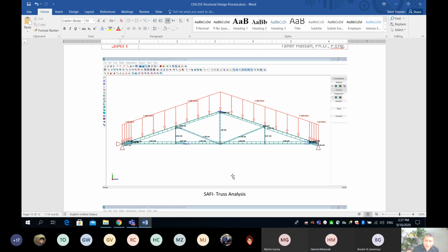Guys, I think I answered this in the discussion, but some of you were probably not really paying attention. If you load the truss only at the nodes where the members connect, all your truss members will have axial force only. Because the top chord is loaded along its members with a uniform load, the top chord will have compression in addition to bending moment. Hopefully this makes sense for you.